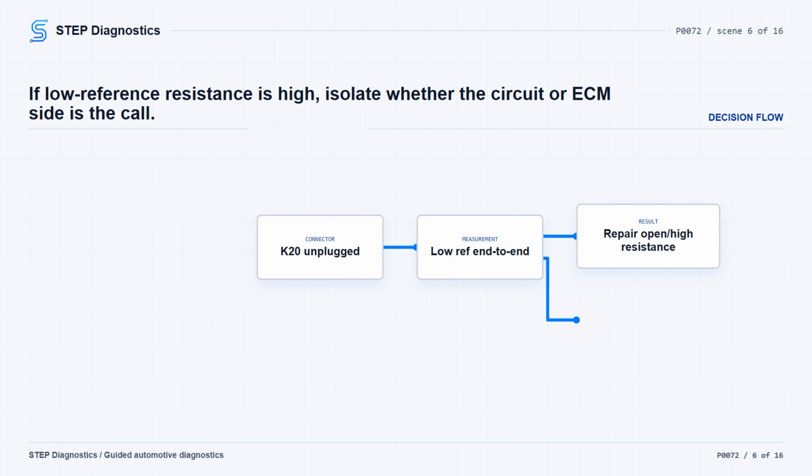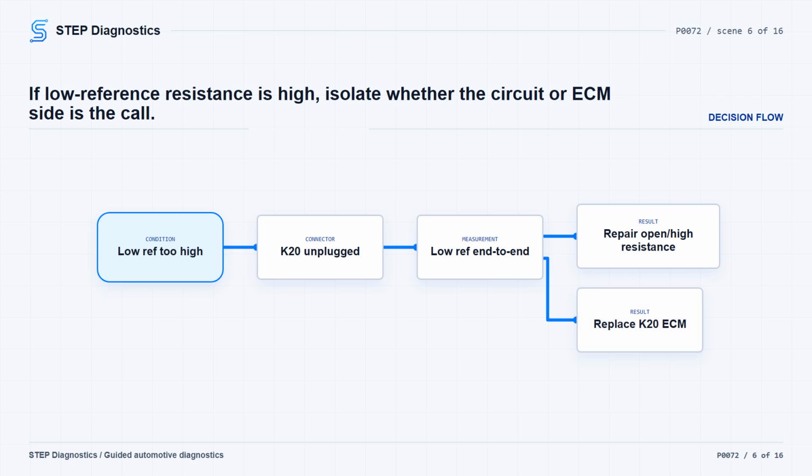That value also needs to be within 15 degrees Celsius, 27 degrees Fahrenheit. If it is outside that range, move into circuit testing. If it is within range, the check is okay at that point. When available, the ECM ambient air temperature calculation reset can help the displayed temperature update more quickly.